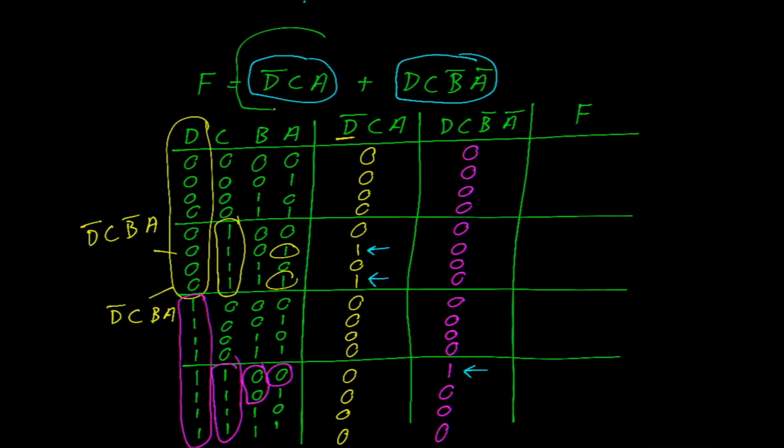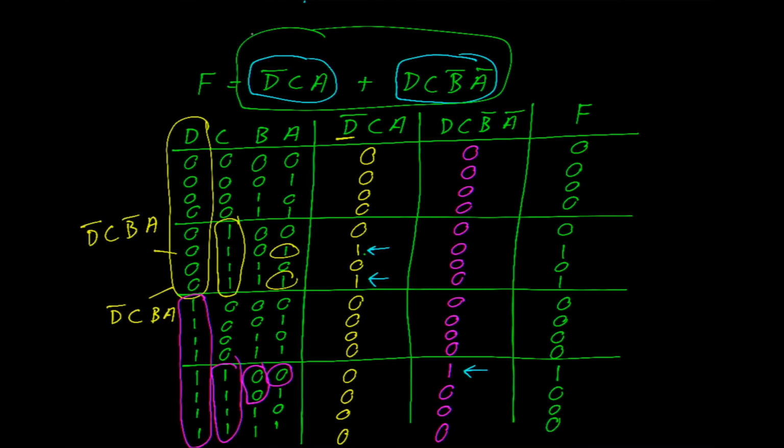Okay, putting this all together, we are going to perform an OR operation on these last two columns. That becomes 0, 0, 0, 0, 0, 1, because of that 1 there, 0, 1, and then 0, 0, 0, 0, 1, 0, 0, 0. Without too much effort, we can convert that into a gate level circuit. Just for convenience, I'm going to record our Boolean expression here using the array style.